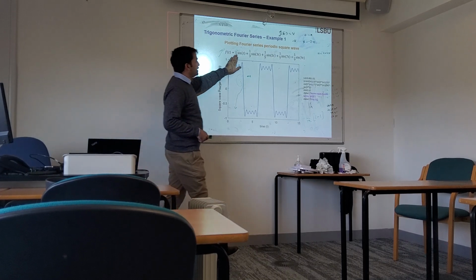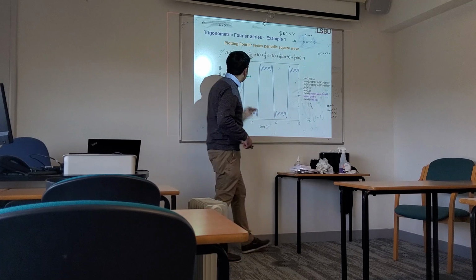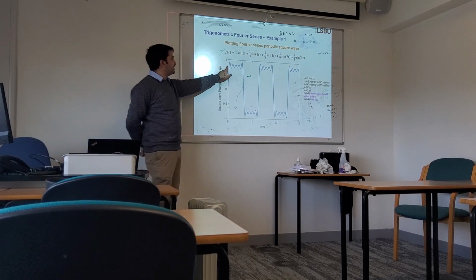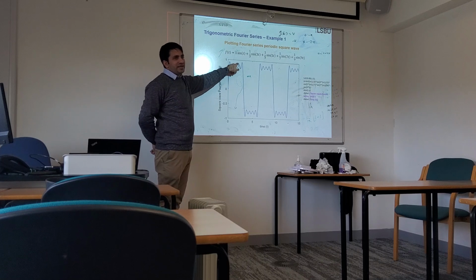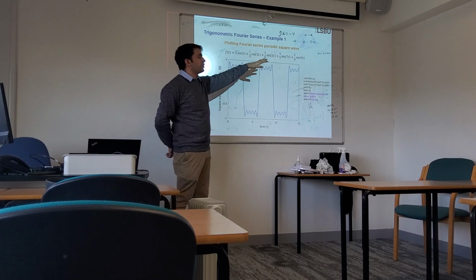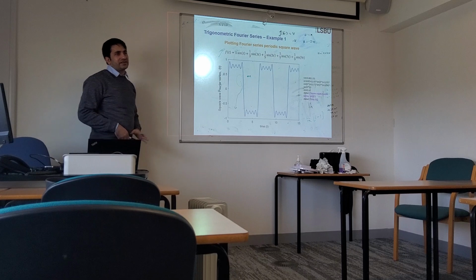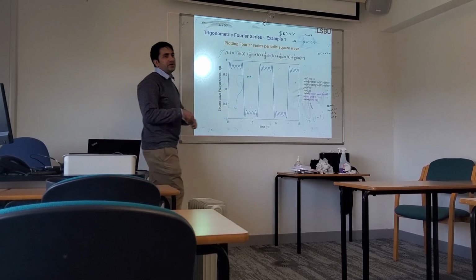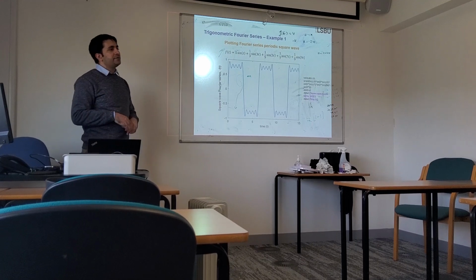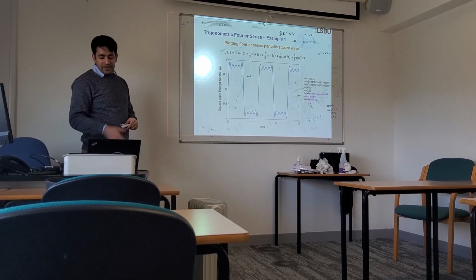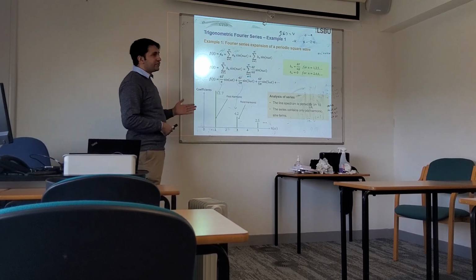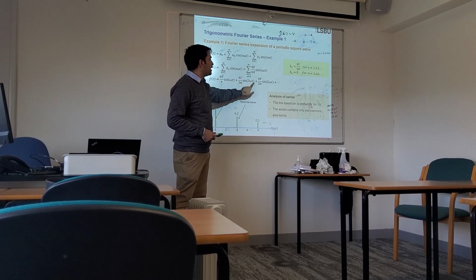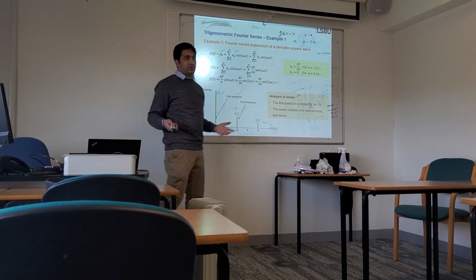And when I plotted this signal with 9 terms, you can see that it is more or less giving us a square wave. But you can see that the square wave was straight. Here you can see a sine shape, because we have approximated it with a smaller number of sines. If we take more sines, you will see that it would be a straight signal. But now we came to know that we have a square wave, and inside the square wave we have omega frequency, we have 3 omega frequency, we have 5 omega frequency, and so on.